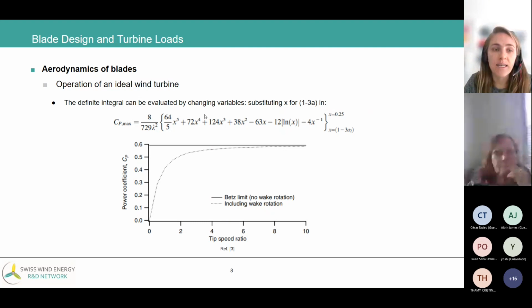And then, for example, this equation here that you were saying that you have never seen is an equation for an ideal turbine and takes into consideration only the wake rotation. The tip losses and other losses are not presented here. That's why, if you are doing this for a thesis, it's maybe not the best.